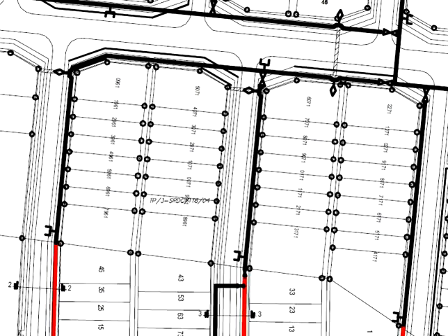Now, the water supply agencies will need to record the consumption rate of the water so that the building owners may be charged accordingly. That is the first reason. You will need to allow access for the operators recording the water meters on a monthly basis. That's why you put the water mains in front. Putting the water mains at the back of the building will disturb their access to the water meters.